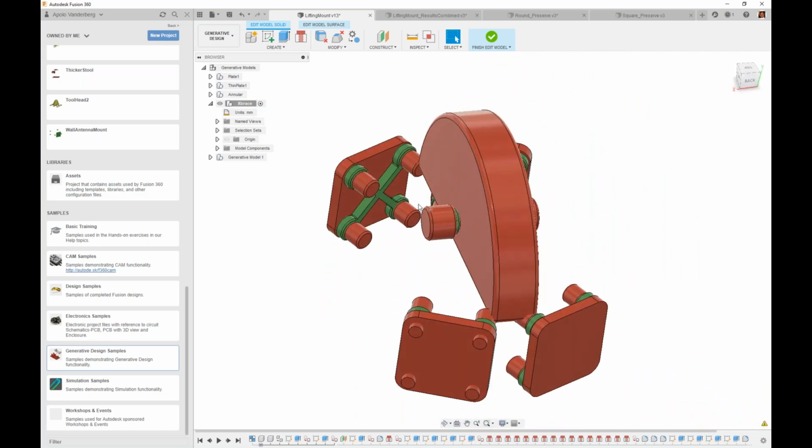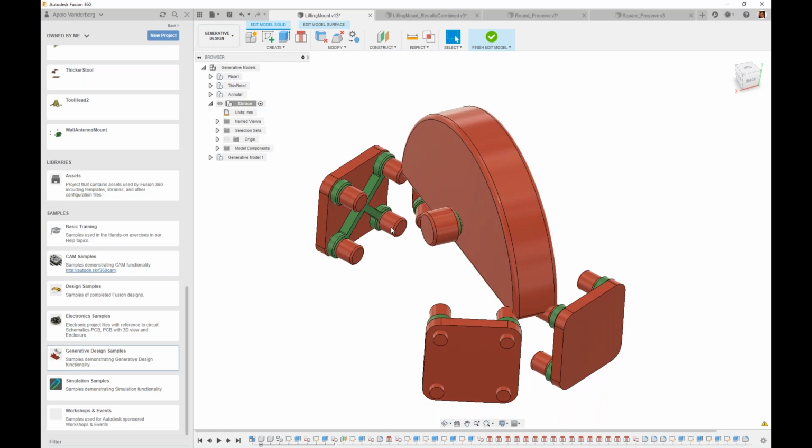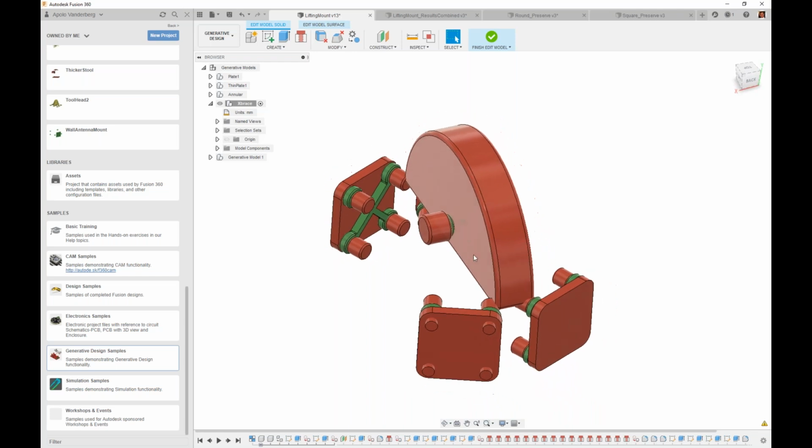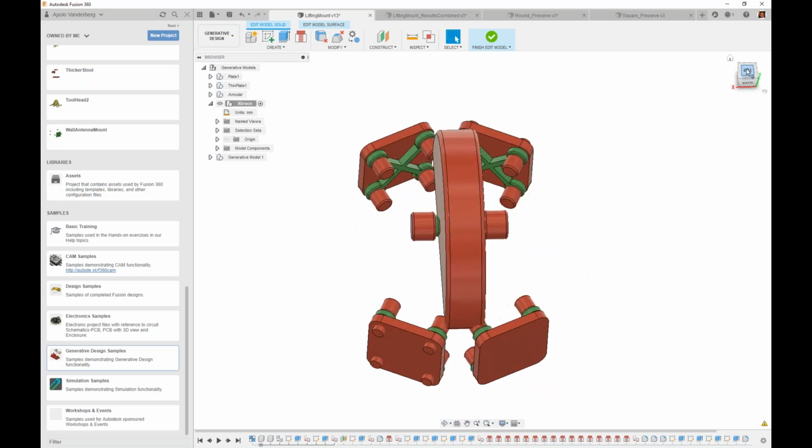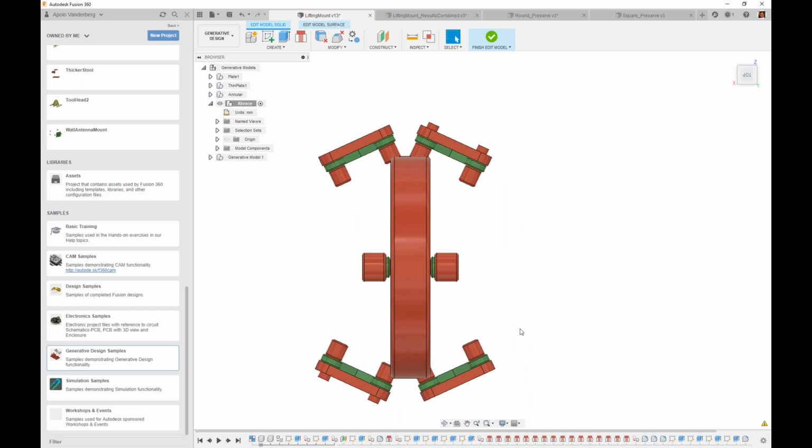If I wanted to limit where geometry can be created, and you're talking about a quadcopter, and this was my top-down view with the 4 green locations where the hubs would be mounted, then at that stage I could design obstacle regions to force geometry only to be built in those locations, or only along certain paths.